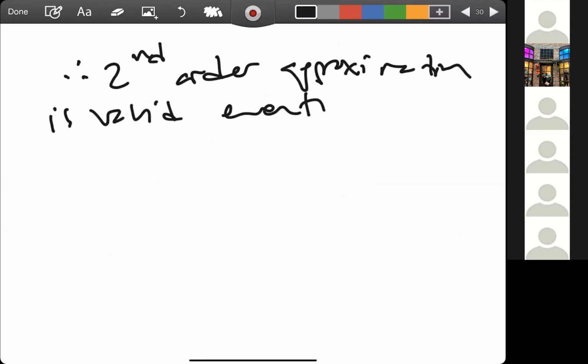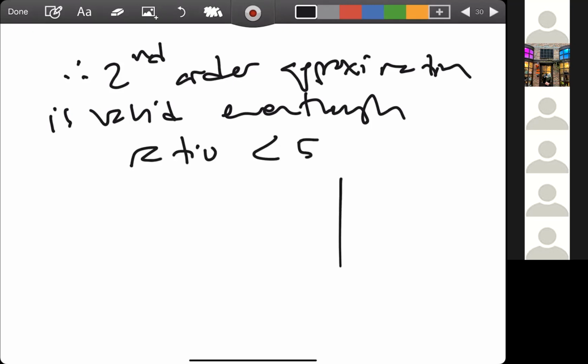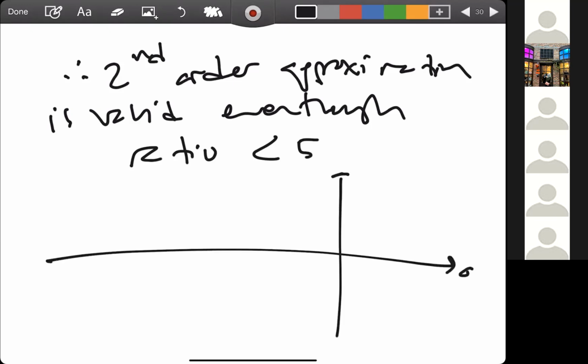So doctor, if they're close, they just cancel out each other, even though the ratio is less than 5? If you look at the plot, the zero is at minus 3, and the third pole is at minus 3.18. And the rest of the system is minus 4 and minus 2 plus minus j1.